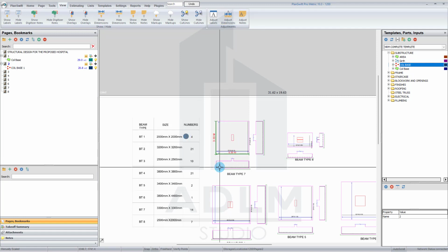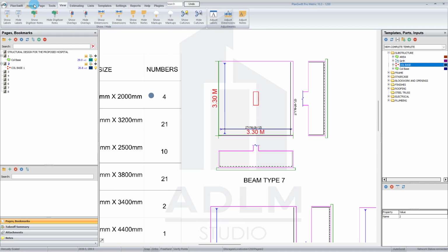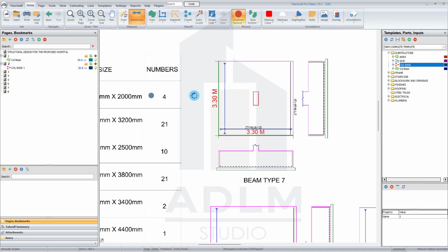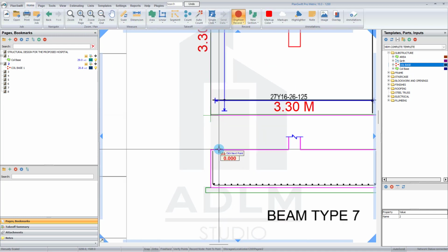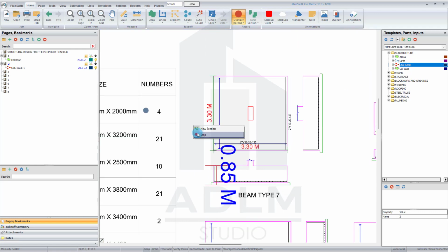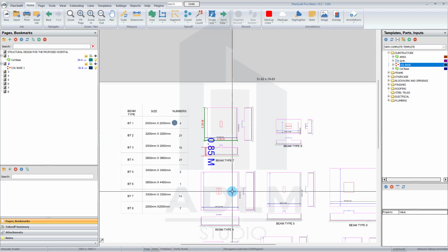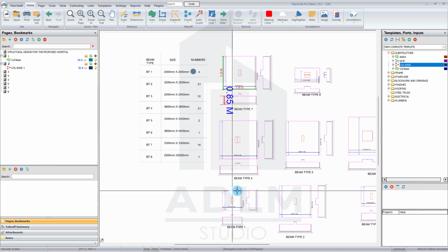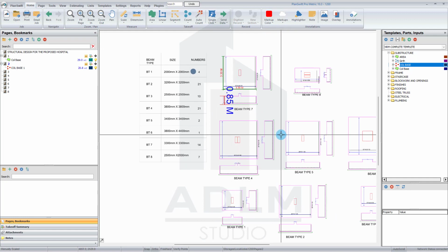Okay, once you've done that, now let's verify my thickness of this by just using the dimension tool here. Let's pick from the top here, from this top down to the bottom. That's 0.85. So you've seen it's 0.85. On an average, most of this column base is 0.85 thick. So that we'll be using excavation depth of 2.85, right? Because we have the starter going across 2 meters. So that is how you would go about that.